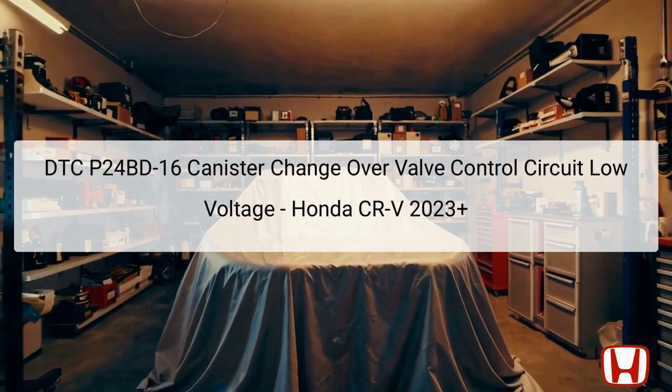The Powertrain Control Module, PCM, monitors this circuit and registers an error when it detects a return signal from the canister that is inconsistent with its commands. In essence, the PCM determines that there is an abnormality if the CCV signal is closed when the PCM is not in the process of sending a closed signal to it.